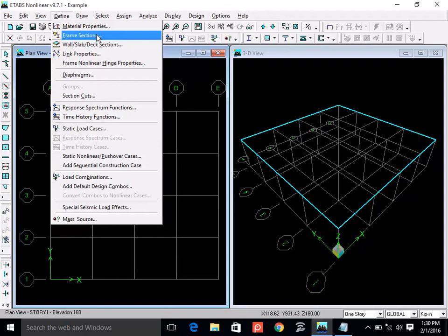12 feet span, beam is 12 inches. 30 feet, 30 inches. 24 feet span, 24 inches beam. If it is a 25 feet span, then you have a beam of 25, but instead of 25, you can round it off to 3 inches. So either make it 24 inch or make it 27 inch. And this includes the depth of the slab.